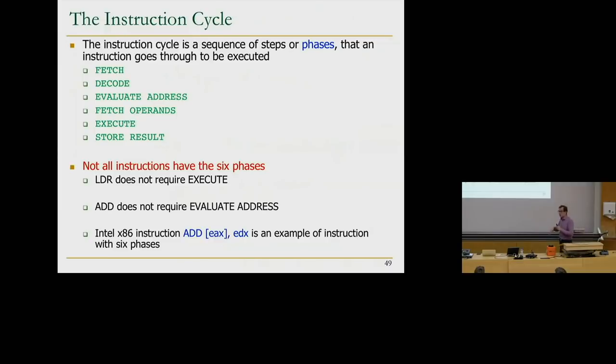So the instruction set architectures we're going to examine are register-to-register architectures. You basically don't have operands coming from memory. You cannot operate on those operands. You basically operate only on the registers. If you want to operate on a memory location, you need to first load it into a register and then do an ALU operation on it. Okay.